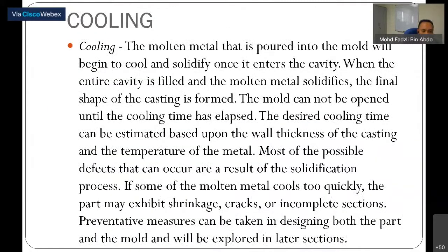And then cooling. Okay. The molten metal that is poured into the mold will begin to cool and solidify once it enters the cavity. When the entire cavity is filled and the molten metal is solidified, the final shape of the casting is formed. The mold cannot be opened until the cooling time has elapsed. Maksudnya mold tu awak tak boleh buka selagi tak sejuk.